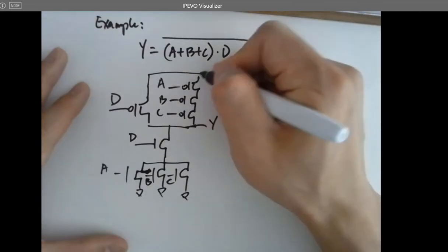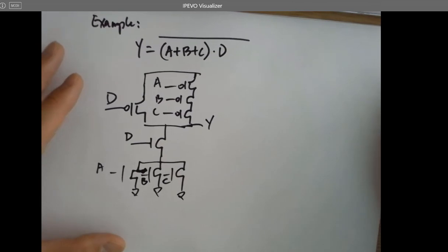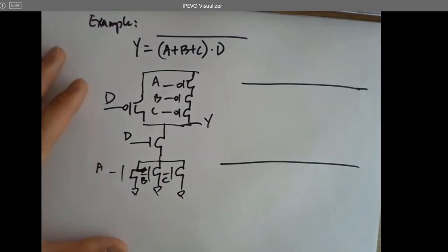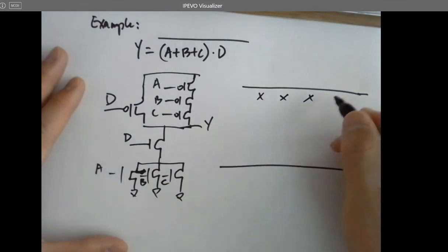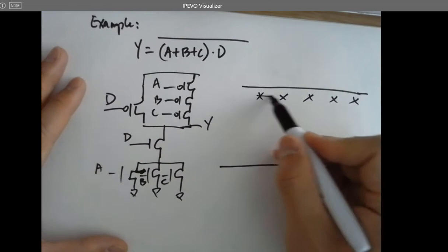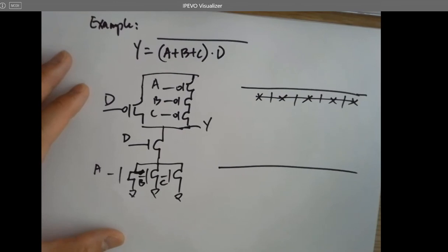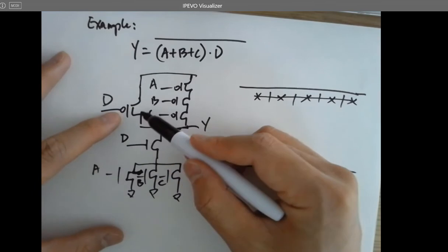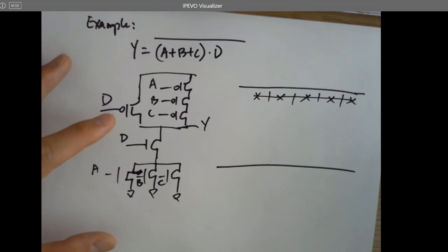And how to lay it out? Look at the PMOS first. I have 4 PMOSes. One, two, three, 4. 3 PMOSes in series and 1 PMOS in parallel with these series PMOSes. That's not difficult, right?